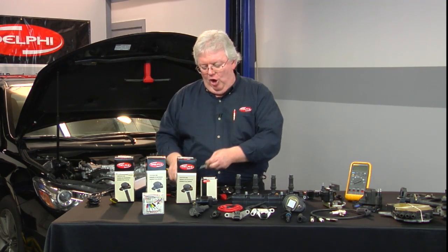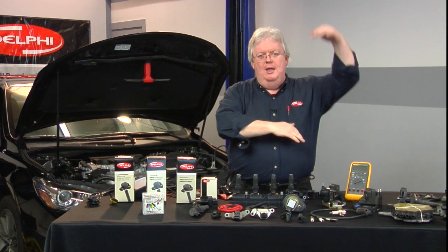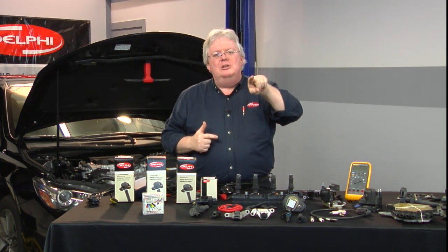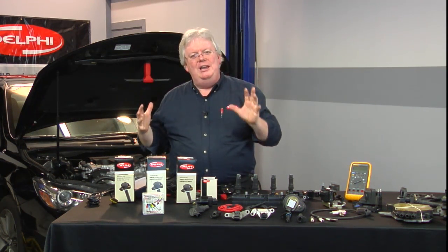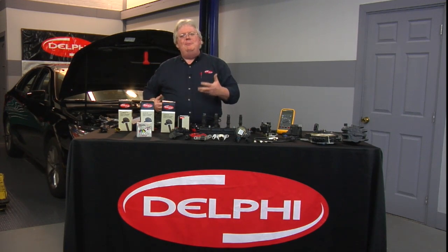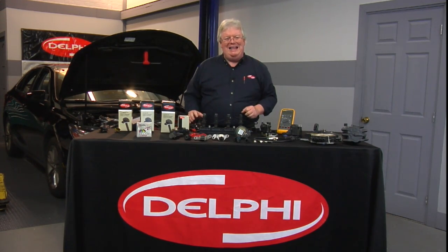simply look at all the patterns at once. Span the time out on your scope, left to right is time, up and down is always either volts or amps, and look at the signatures of those current ramp ups of those coil events. When you find one that looks radically different than the others, that's the one that's intermittently breaking down, and that's the one you have to address with new parts or at least further diagnostics.